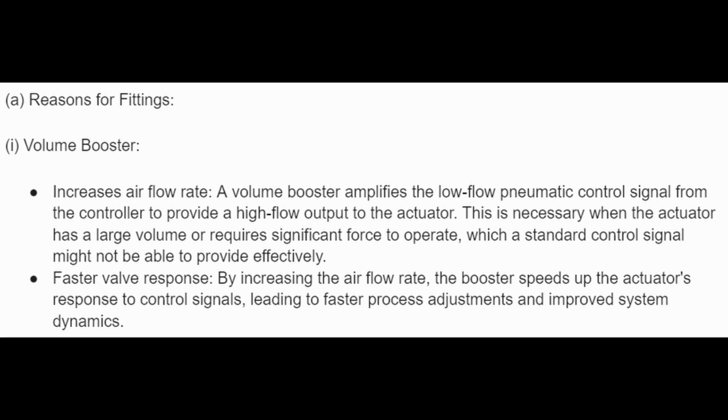Reasons for fittings. 1. Volume booster. Increases air flow rate. A volume booster amplifies the low flow pneumatic control signal from the controller to provide a high flow output to the actuator. This is necessary when the actuator has a large volume or requires significant force to operate, which a standard control signal might not be able to provide effectively.